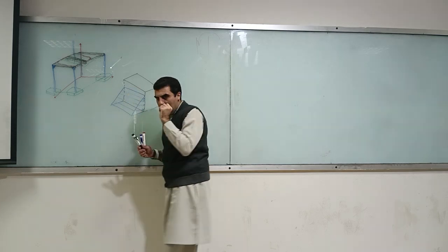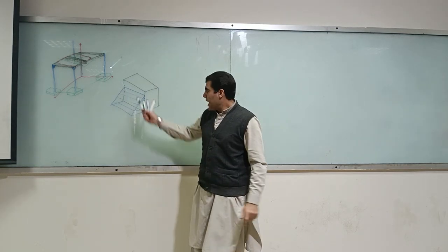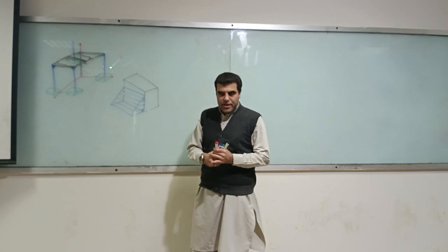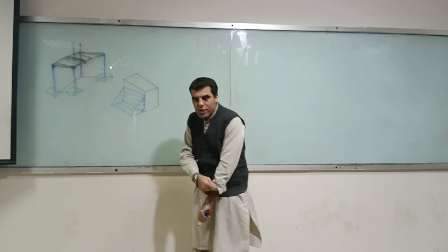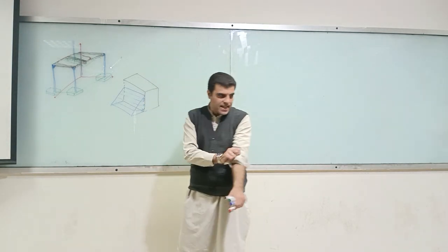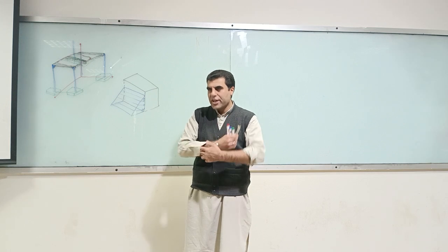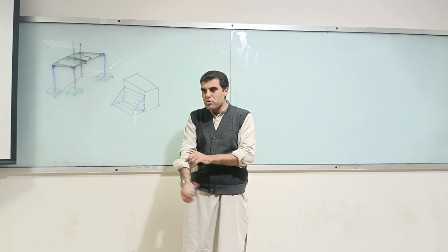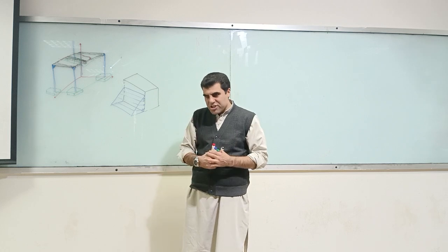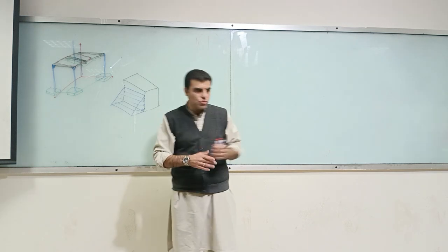This is a dam which is subject to hydrostatic load, which is normally a uniformly varying or linearly varying load, isn't it? Yeah, your hydrostatic load is normally linearly varying. You are doing fluid mechanics, aren't you? Yes, so the hydrostatic load is always considered as uniformly varying. Why? P is equal to gamma h. So as you go deeper into a body of water, your pressure increases.